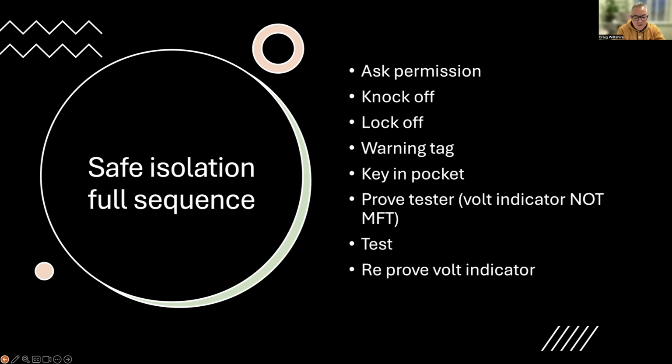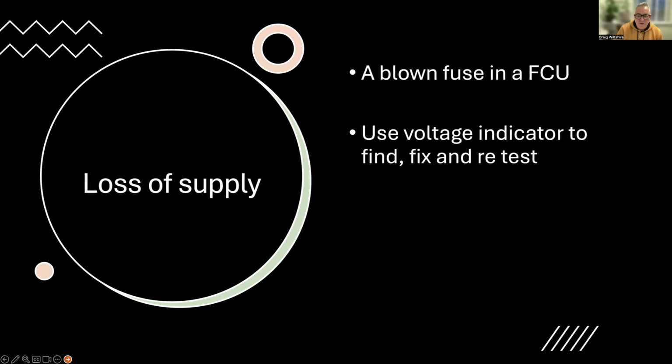Now, I'm not needing you to do all the faults or all safe isolation for every single fault, right? But what I do need you to do is this. For every fault that you show a story of, the board must be locked off. If you're working on a board, it's locked off. If you're working on a circuit, it's locked off. If you don't show me the MCB or the main switch locked off, we can't accept the fault. They make us refuse it. So even if you don't do it, guys, just make sure you lock that off, right? So that's safe isolation.